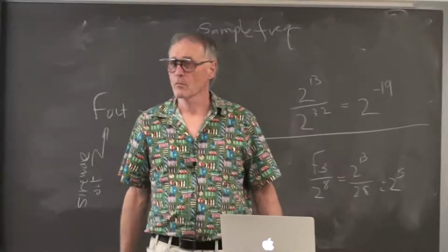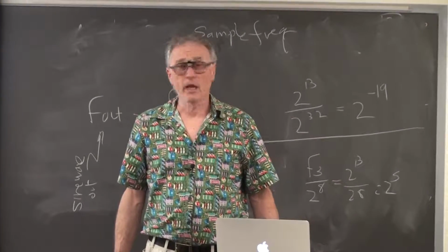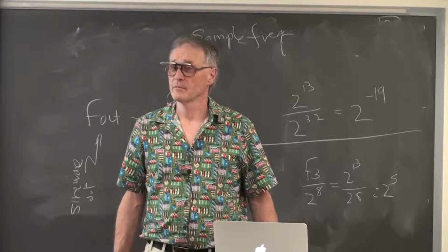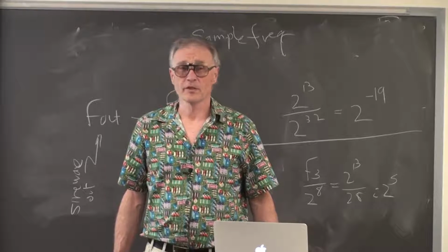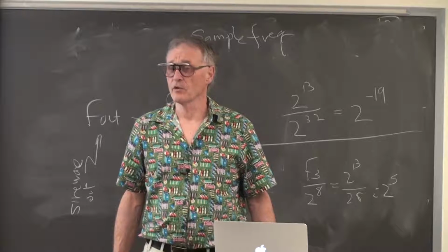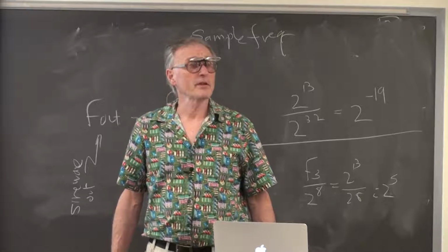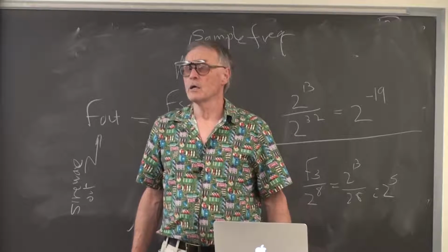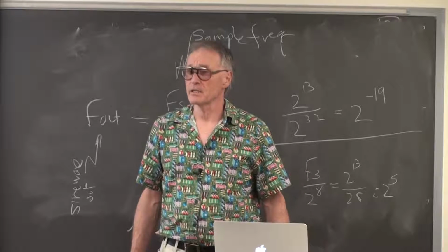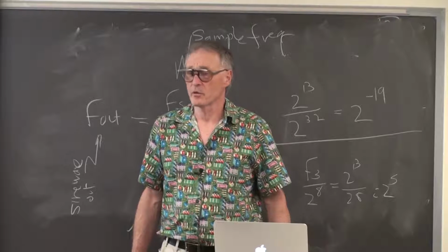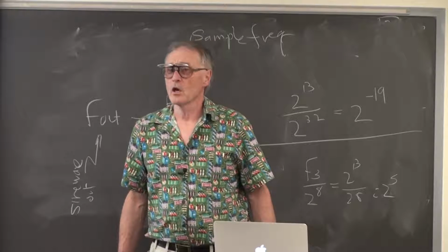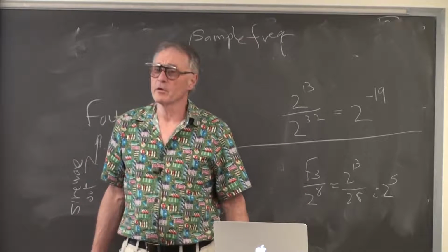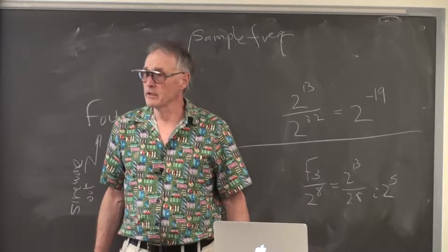Is it the same if you use float? You cannot use floats. They're not fast enough. You have to use fixed point. I think you'll find that you won't be able to go fast enough. I believe that a floating add takes 80 or 90 cycles, and a floating multiply is 30 or 40 cycles. So I think you're not going to be able to go fast enough. But I'm not sure. Have you tried it? Yeah.